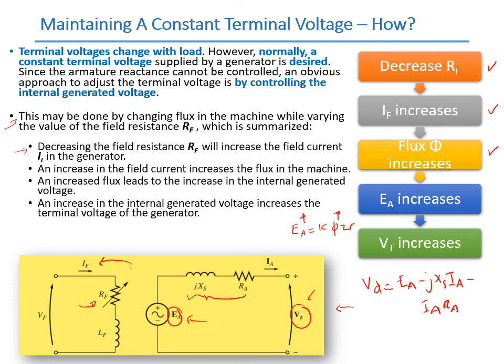Okay, and then the terminal voltage can be equal to V pi or square root of 3 times V pi, depending on the connection. Yeah? The three-phase connection. Yeah. Okay, and Vt equals V pi for the delta connection. Okay, so from this, we can see that we can control the terminal voltage or the output voltage by adjusting the field resistance. Yeah?